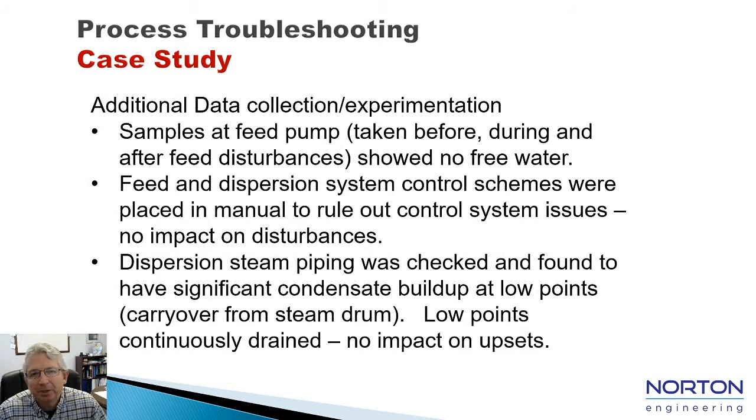Additionally, some additional data was collected, and we did some experimentation to try and figure out what was happening. So we're generating hypotheses and testing those to try and rule things in or out. Samples were taken at the feed pump. They were taken before an upset, during an upset, and after an upset, and there was no water identified.